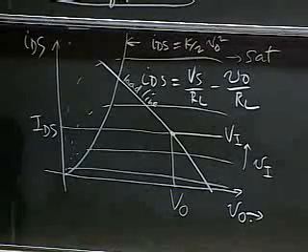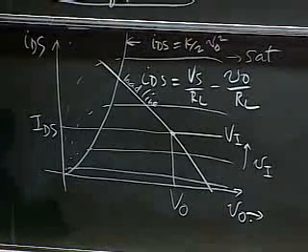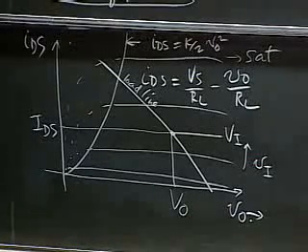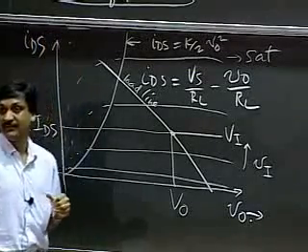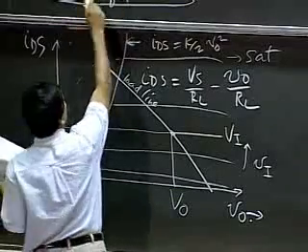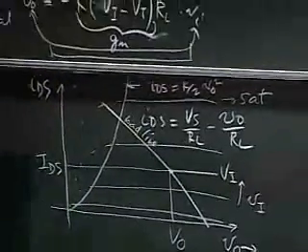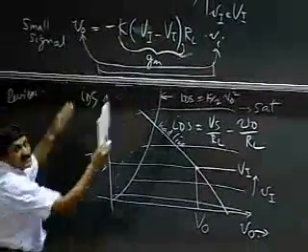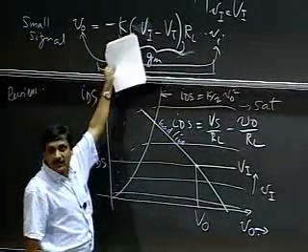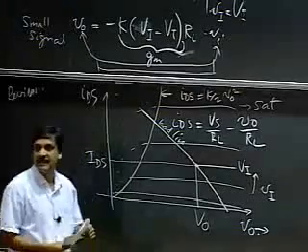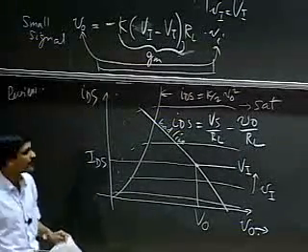Okay, so far there's nothing new. One thing we stopped at last time was pointing out the gain of our amplifier. This is the gain, minus K (VI minus VT) RL, that's the gain A of the amplifier. That gain is related to VI. The gain was proportional to VI minus VT. So therefore, if I increased VI, I would get more gain.